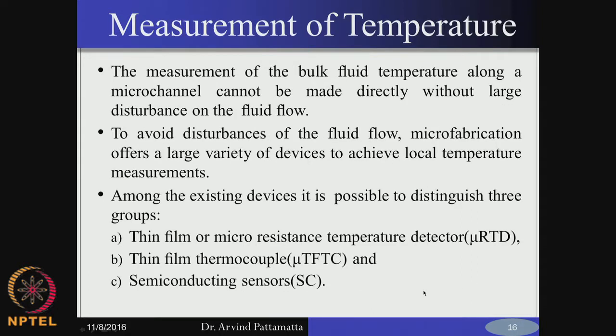Now, in today's class we will look at the other two, which are the temperature and flow measurements. At micro or nano scale, of course, at nano scale there is no point in defining or measuring a temperature, but at the micro scale, of course. When you are talking about conventional thermocouples, you have a junction of basically either chromium, aluminum, so you have different thermocouple elements which you make a junction, which produces an EMF based on the Seebeck coefficient of this particular thermocouple junction.